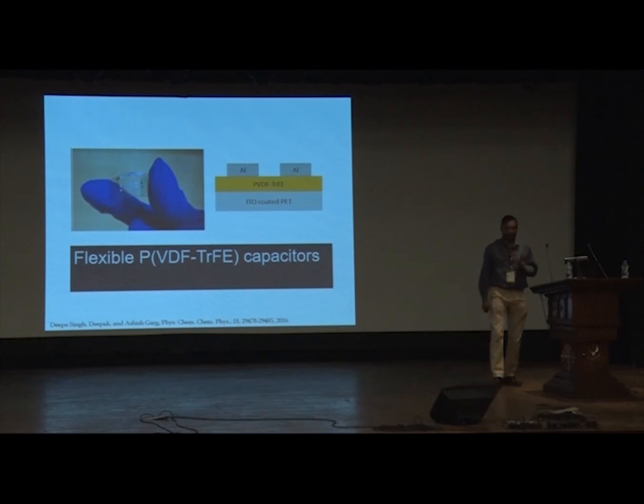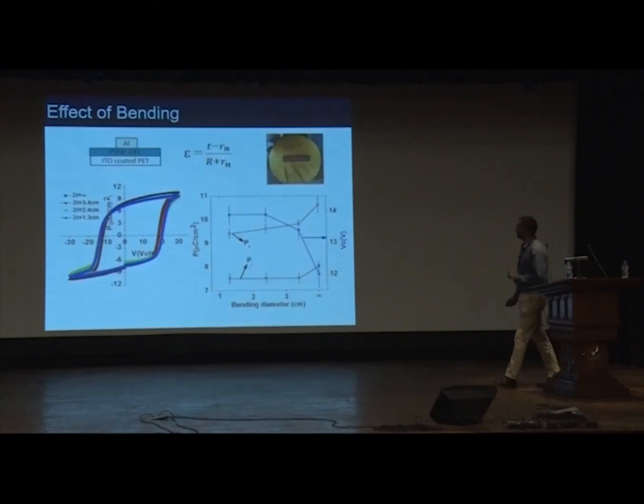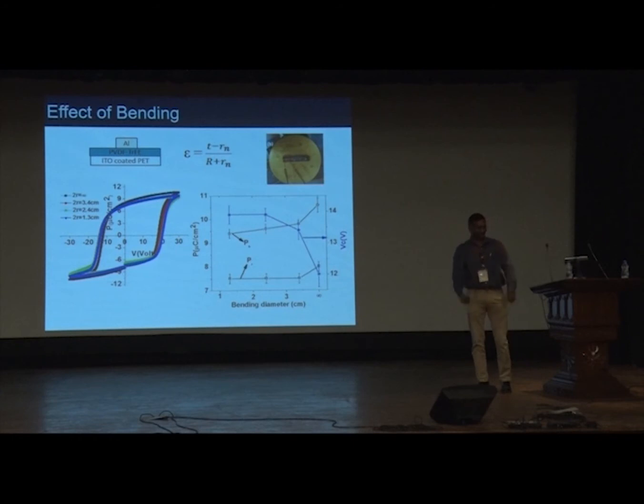Now, when you work on a flexible memory, it should undergo not only a number of electrical cycles, but also mechanical strains. So what we did was we looked at the effect of both mechanical and electrical switching on the device. So you have a configuration like that. We wrapped the memory around an AA or AAA battery, which is a very large strain. I mean, your debit card or credit card will not flex that much. So we really flexed it completely just to look at the effect of extreme strain.